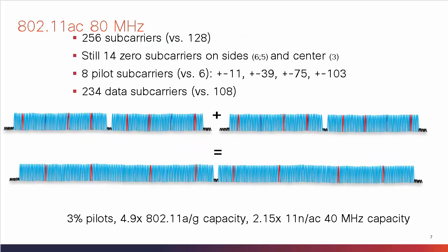But back on the channels, if you look at what we've been doing, every time we've been changing from 20 MHz to 40 and to 80, we've done two things. Reduce the number of null channels on one side, and also reduce the number of pilots on the other side. This is great on paper because it allows for more channels used for data transmission. But every time you reduce the number of pilots, you also lessen your ability to know what the noise figure is between those pilots.